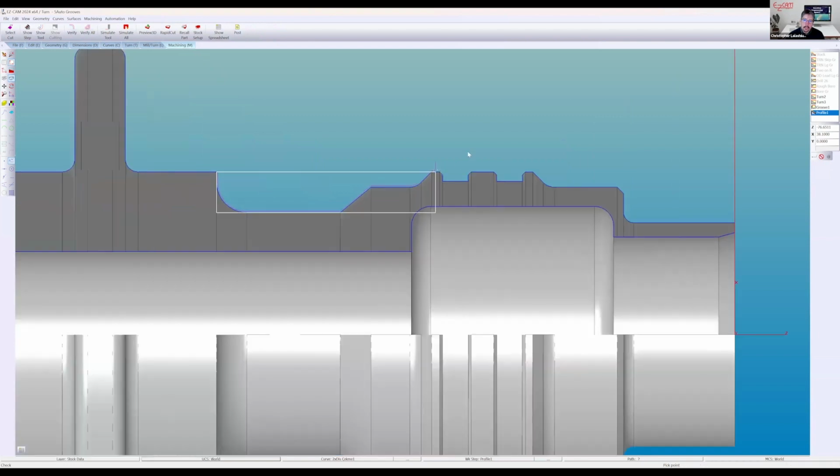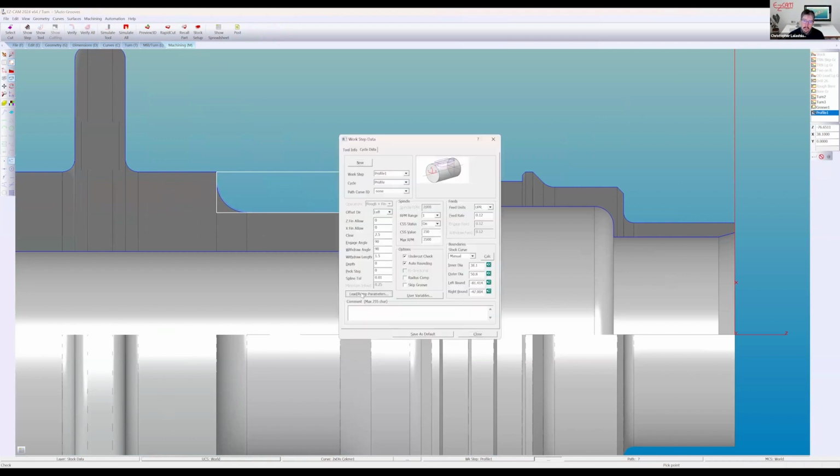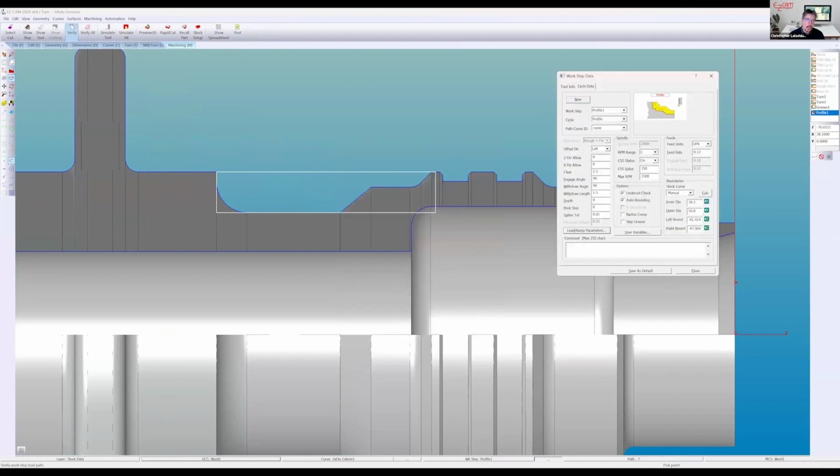All right, let's add an arc into the work with lead and ramp. I'll start inside the groove, so that would be 3 millimeters. I'll just put this window aside so we can look at our toolpath while the operation is open.